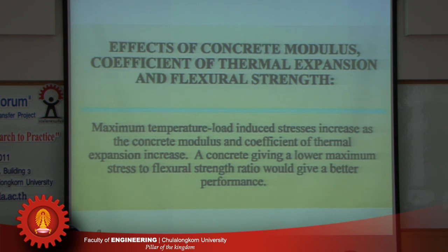Okay? And having a stronger concrete may not help because your stress may be so high that even though you have a higher strength, it may not compensate for the increased stress. A concrete giving a lower maximum stress to flexural strength ratio would give a better performance.